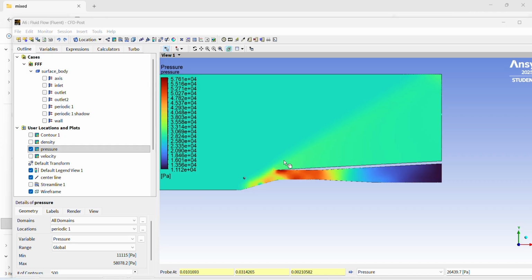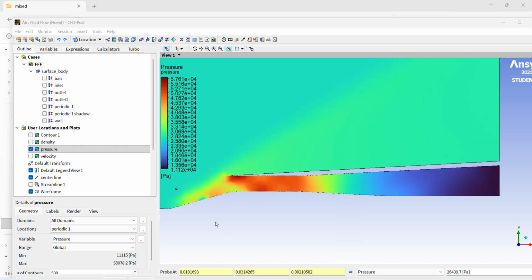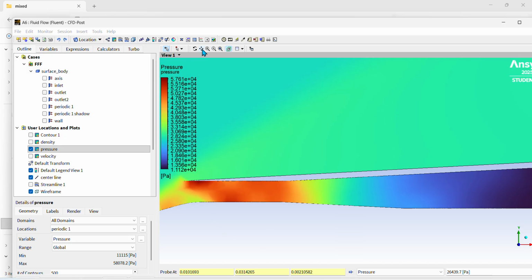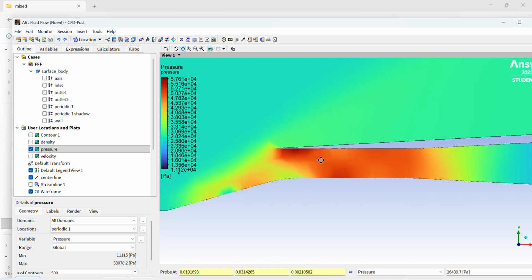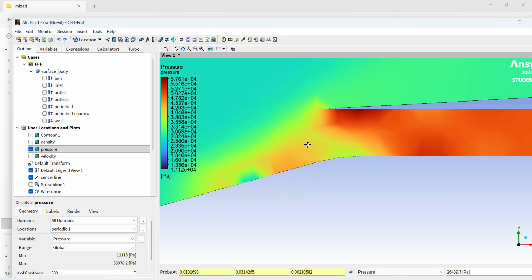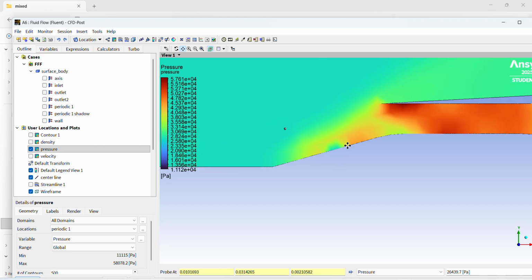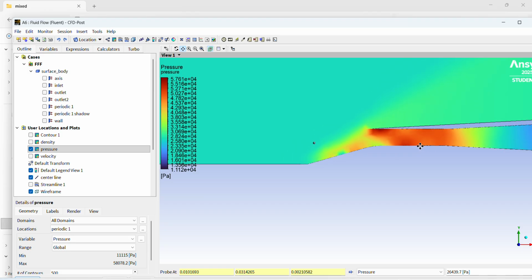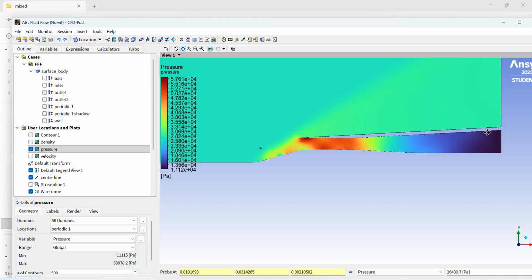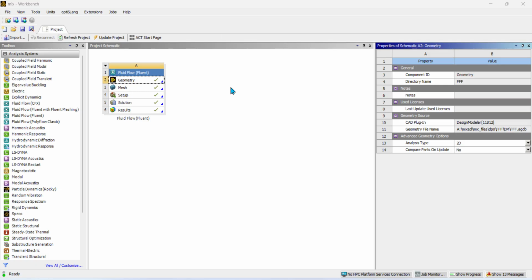Now, here you can see the bleeding is actually happening here. You can see the bleeding actually happens here because we created a slot here. So the mass is discharging through this hole. When it is happening, we obtain the highest pressure recovery at the end of our mixed supersonic intake system. Now this is our single bleed hole.